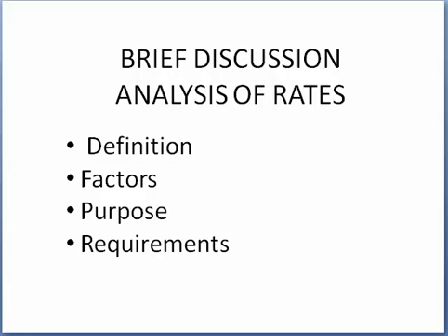Then, to revise the rates worked out by the analysis due to an increase in labor cost or material cost. If we are working at a particular site and the material or labor involved for that particular item varies in rate, and the rates are not in a match with the detailed analysis of rates as specified by the Central Public Works Department, we need to calculate the revised rates. To calculate those revised rates, analysis of rates is very important.